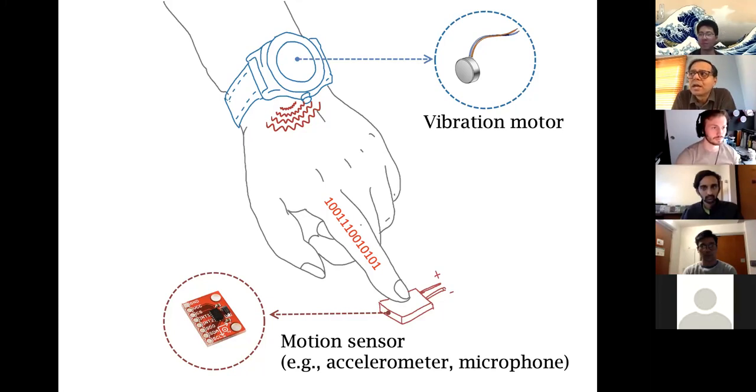What is the sampling rate that you have been using for your MP? Do you know? Yeah, 100 hertz. So 100 hertz is common, but you can also get 200 hertz in some of these good phones. Because accelerometers are typically not used for very fancy applications, they give 100 hertz. But in a gaming mode, or some mode, you can make it 200 hertz. And maybe there are some special cases where you can get 500 hertz.